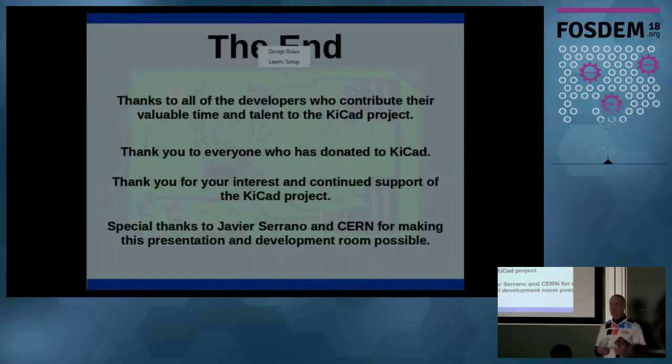You may not get the exact same polygon that you get from Eagle. So it's not going to be a slam dunk on every project, but the level of import and the quality is really good. It's a really nice feature for folks trying to convert, and that's true of any EDA. I've never used a piece of EDA software that imported somebody else's that did it perfectly. There are always subtle differences that you, as an engineer, just have to look for.